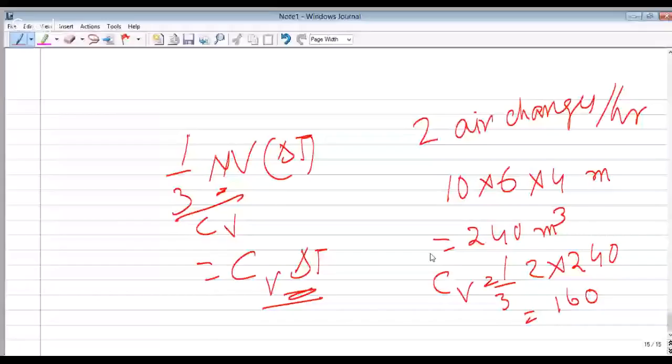Then if I want to find out the sol-air excess, or the amount of heat that will come through, first, how much is the temperature? That is alpha I divided by H naught. Let's say I have an opaque surface, for which alpha is equal to 0.4, and H naught is the same 12, we will take.